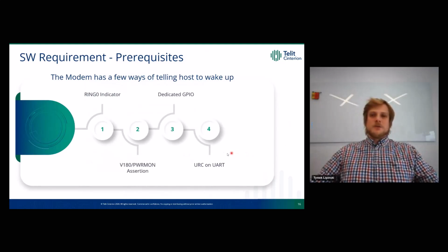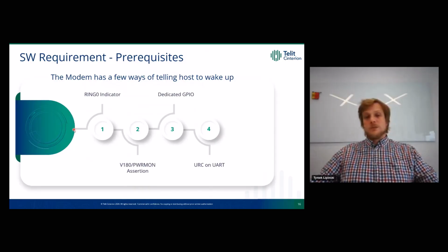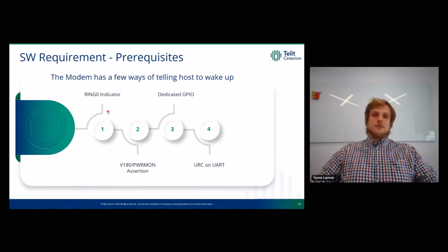How do we wake up our host? So let's assume our modem finished the PSM time and it wakes up. So what does it do to wake up the host? So most commonly used is the ring 0 indicator of the serial interface. If that's not available or we have another solution, we use V180 or PowerMon assertion. So that's a pin available on the module BGA footprint that goes high when the module leaves the off state or deep sleep state.